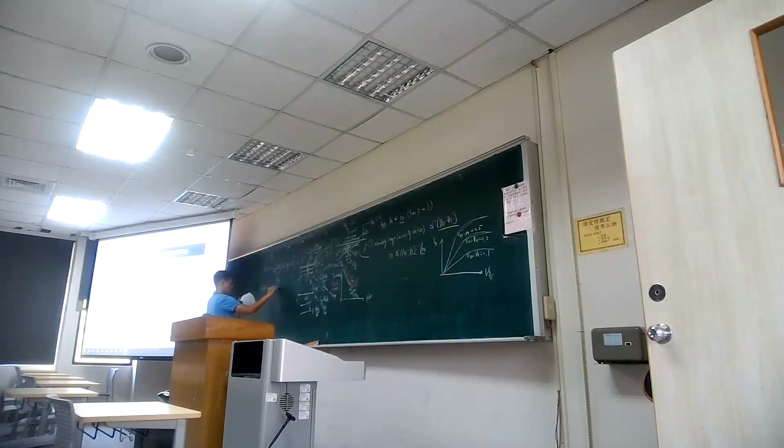which is proportional to q n mu n E. Because the carrier conducting here is the electron, we consider the mobility of the electron, the number of electrons, and q, multiplied with the electric field.